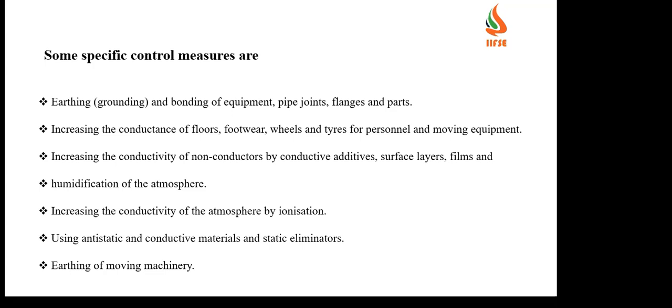And increasing the conductivity of the atmosphere by ionization, and also using anti-static and conductive materials, and also static eliminators. Eliminators means conductive flooring, conductive materials, and also anti-static shoes. By this we can control static electricity. Then earthing of moving machineries. Whatever moving machineries, rotating parts, and portable moving machines or equipment, all those machines should have proper earthing to discharge the accumulated energy during the operation.